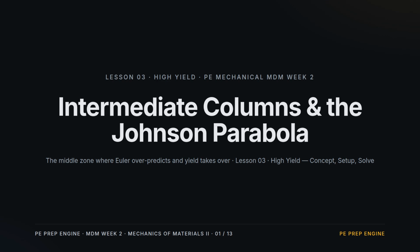Week 2, Lesson 3, Intermediate Columns and the Johnson Parabola. Lesson 1 classified the column. Lesson 2 loaded a long one with Euler. But Euler assumes the column stays elastic, and as the slenderness shortens, its predicted stress climbs until it would pass yield. In that middle zone, Euler overpredicts. Today we find the boundary and the formula that governs there, and close out the buckling arc.